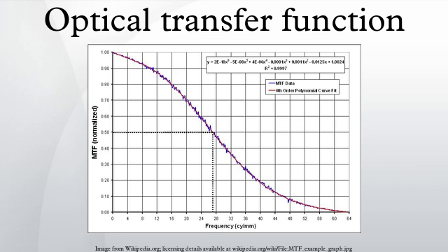Using a grid of black and white lines: although sharpness is often judged on grid patterns of alternate black and white lines, it should strictly be measured using a sine wave variation from black to white. Where a square wave pattern is used, not only is there more risk of aliasing, but account must be taken of the fact that the fundamental component of a square wave is higher than the amplitude of the square wave itself. A square wave test chart will therefore show optimistic results. The square wave result is sometimes referred to as the contrast transfer function.